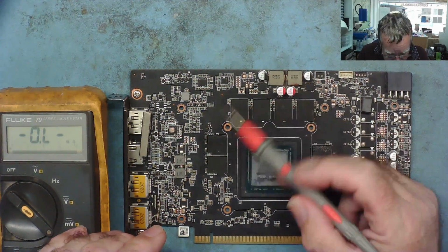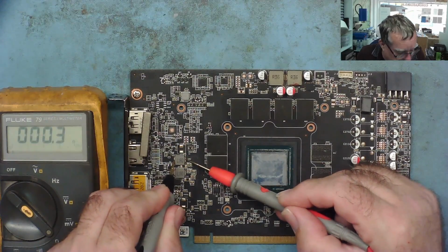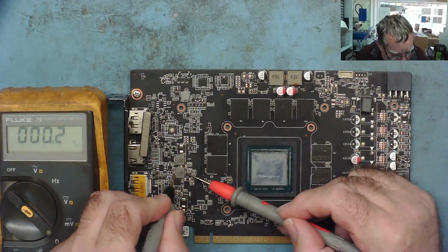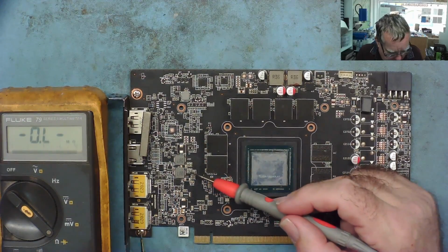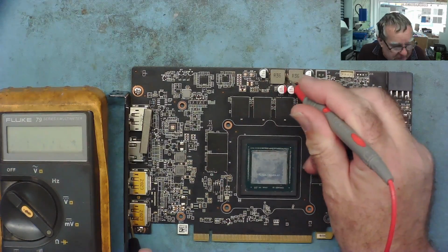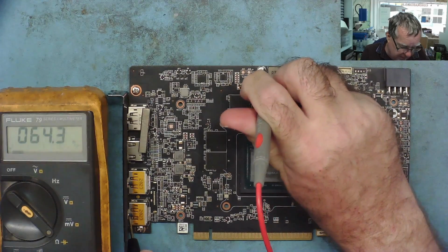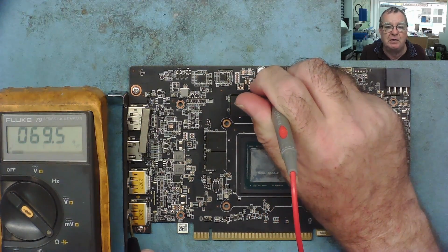One other thing I'll just mention, the resistance of these coils is extremely low, almost zero. So in actual fact, it doesn't matter which side of the coil you measure to ground, you will get the same results regardless of which side you're reading from. So don't think you need to measure from one side of the coil or the other. They will both give you the same readings on a multimeter.